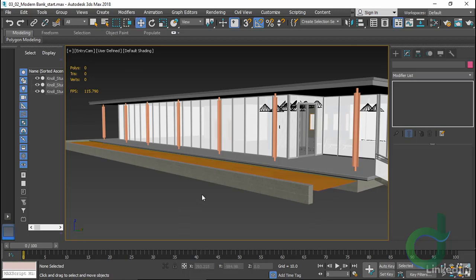There's a lot of instances where we can use this kind of mapping. Block walls, brick walls, anything with a repeating texture that needs to flow around a corner, where in Revit it may not quite handle it well, but with a little bit of mapping adjustment here in Max, we can really make things shine, or rather, look, well, like they're supposed to.